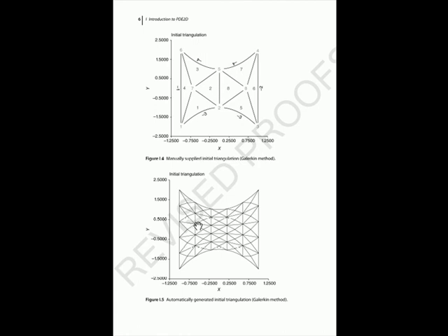And in either case, PD2D will automatically refine the triangulation. So the more triangles, the better. Basically, you're approximating the solution by piecewise polynomials that are different polynomials on each triangle. And so the more triangles you have, the more accuracy you'll normally get. The initial triangulation is basically just the minimum to get you started. Then you say, well, I want 1,000,000 triangles, and you can even say I want it most dense in this area because the solution is changing most rapidly here, and it will automatically refine that, so you don't have to worry about the final triangulation, just the initial triangulation.